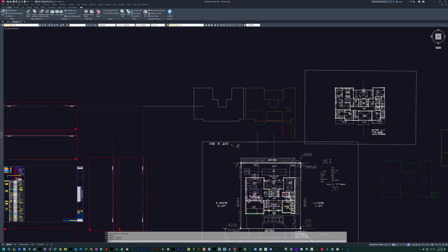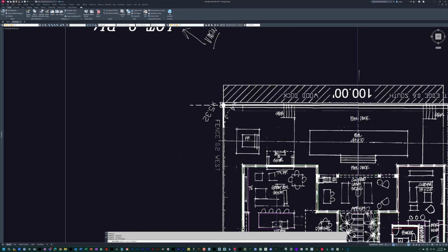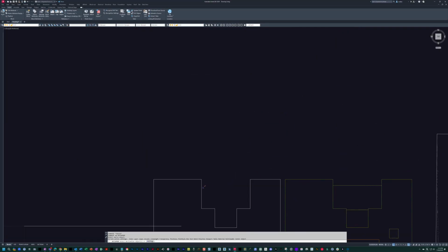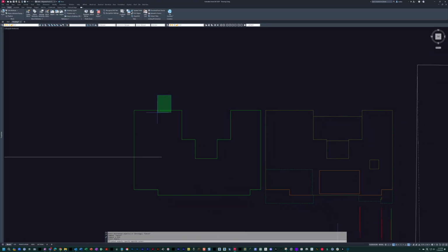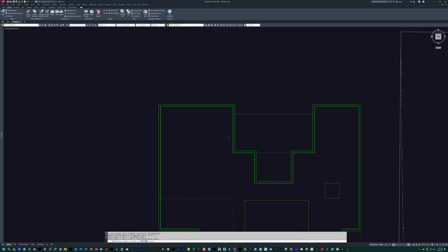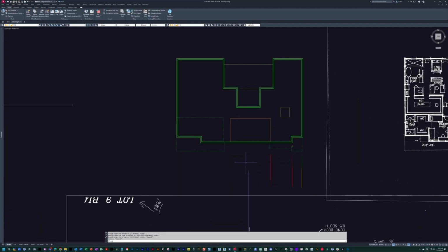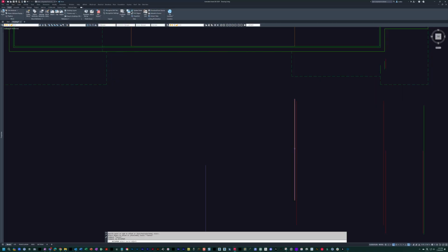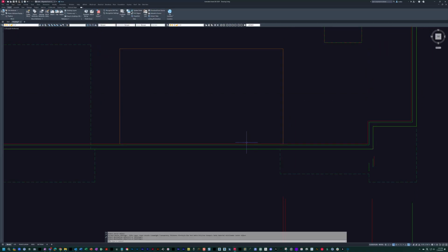And I am going to match this to my exterior wall layer. And we will move this back here, and I can offset this 8 inches. Whoops. Offset 8 and offset 2. This is now a block wall with furring already set upstairs, which is perfect.